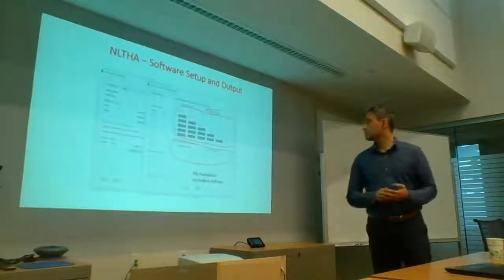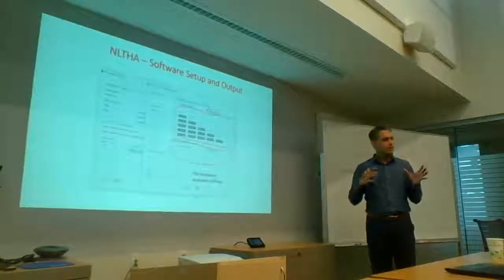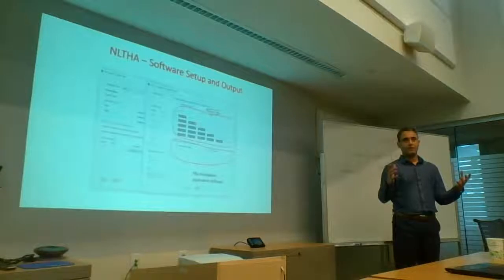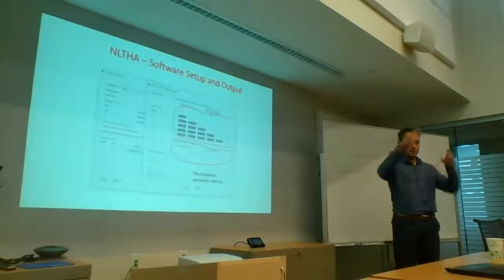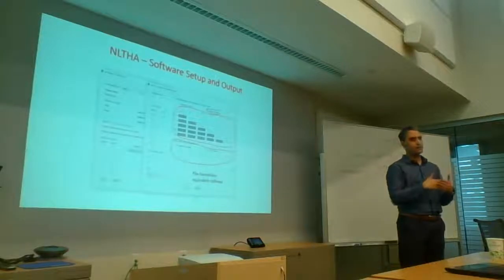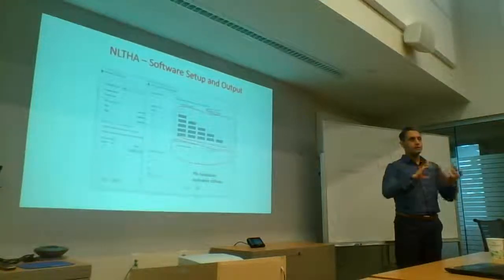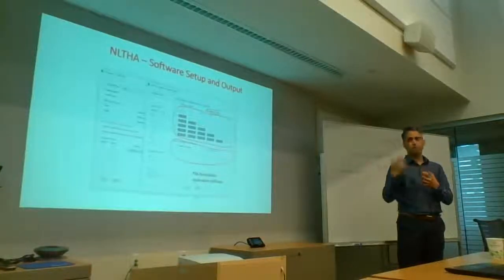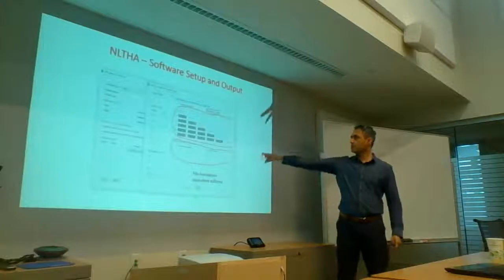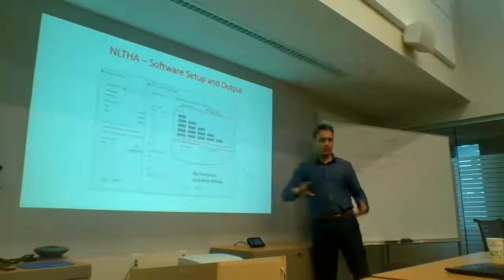We also got some stiffnesses for a pile foundation, but there was a forest of piles. There were about 66 piles. And we didn't want to have 66 piles modeled with their each PY spring. So what we asked the geotech was to do the analysis themselves and come up with an equivalent spring matrix for us that we could use. So they gave us this 6x6 matrix. They mostly had just the diagonal terms, but they found some coupling.